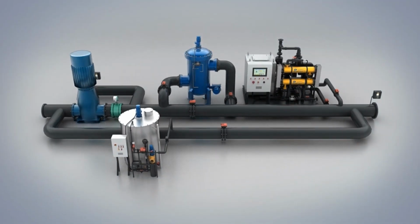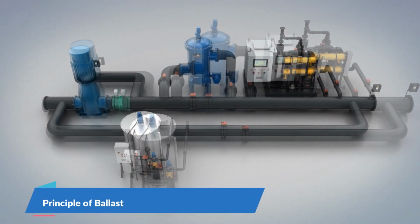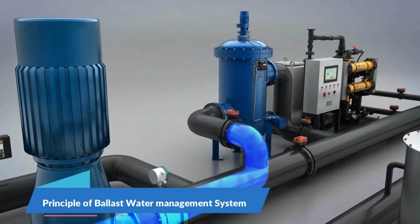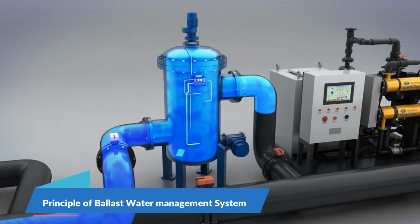The principle of chlorine BWMS mainly consists of three procedures: filtration, disinfection, and neutralization. During ballasting, ballast water is filtrated by an automatic back-flushing filter. Marine organisms larger than 50 micrometers will be removed during this process.